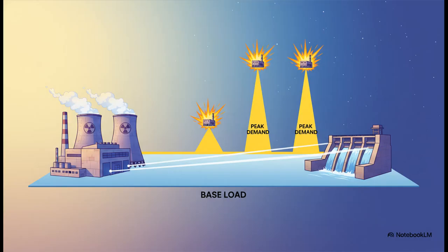And that leads us to the core strategy of the entire power grid. To make those super expensive hydro and nuclear plants pay off, you have to run them all the time, non-stop. They become what are called baseload plants, providing that constant minimum amount of power the grid always needs. This pushes their load factor way up, spreads out those fixed costs, and makes them incredibly cheap to run on a per-unit basis. Then you can use other plants, like diesel, that are quick to start up to handle those peaks in demand.